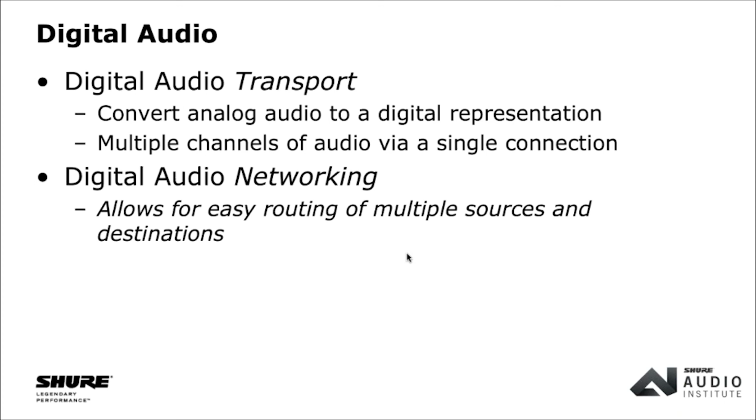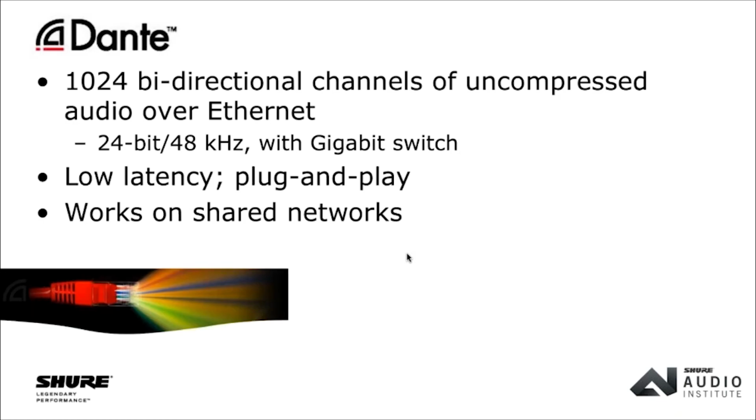Okay, let's wrap up here with a little bit on networked audio and some specific considerations there. Again, networked audio is a way of allowing digital audio, multiple channels or multiple sources of digital audio to reach multiple destinations, often utilizing standard networked hardware. It doesn't have to be the case, but that's where we've moved with protocols like Dante now, where it is basically utilizing a standard Ethernet network for moving this digital audio information around.